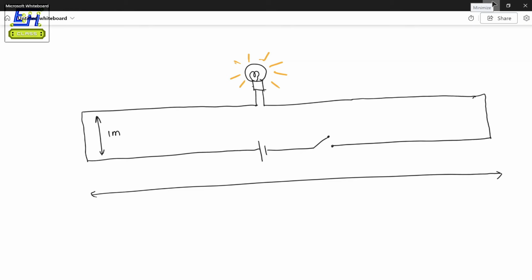So once we press the switch, we complete the circuit, and we can also represent this as capacitance on both sides, because these are just conductors separated by space, even though they are short circuited at the ends. But still, if you see what is present in the immediate vicinity, these are nothing but capacitances. So just by using capacitive coupling, you can imagine, because when you press the switch, it is actually a transient signal which can easily pass through this capacitive coupling.